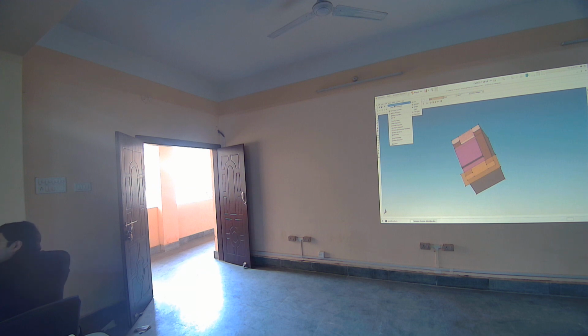In that window, the uniform mesh will already be created. Right? If you don't want a uniform kind of mesh, then you need to go to refine placement, multi-box placement. Right? In there you will define multiple boxes and multiple density of grids that you will be adding.